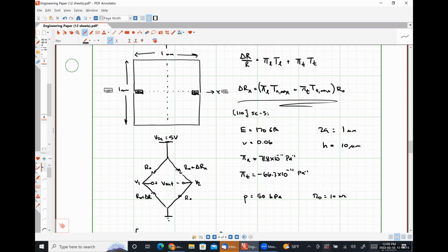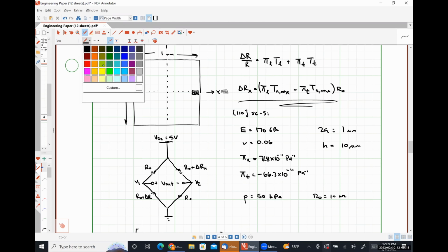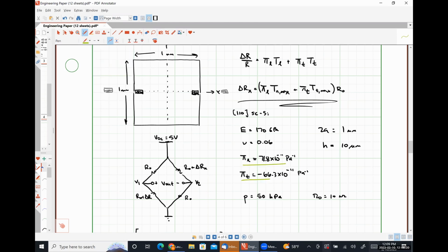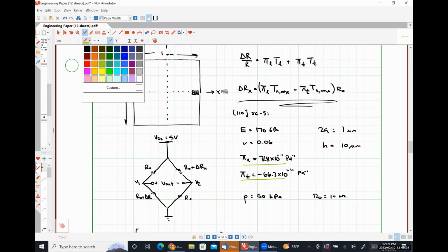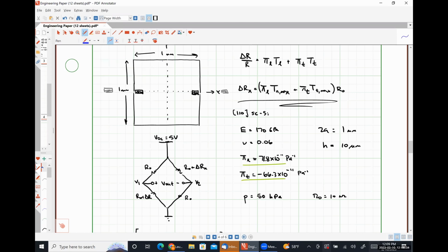Okay. So this isn't an obvious thing, but notice here that our piezoresistive coefficients are of opposite sign. That's pretty much true always, okay? So what you could do to make a better pressure sensor would be to integrate, instead of using a reference piezoresistor pair, another piezoresistive pair oriented in a transverse direction at your other locations of maximum stress, right?